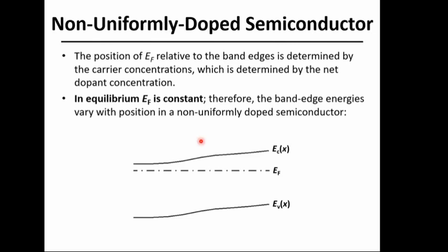Now here, which should have been before doing the Einstein relation, we're talking about the equilibrium of the Fermi level, which usually is constant if we're talking about uniformly doped material, meaning that if I'm talking about, let's say, N-type material, and when I dope my doping substance into silicon and the surface is uniform, the Fermi level will be constant.